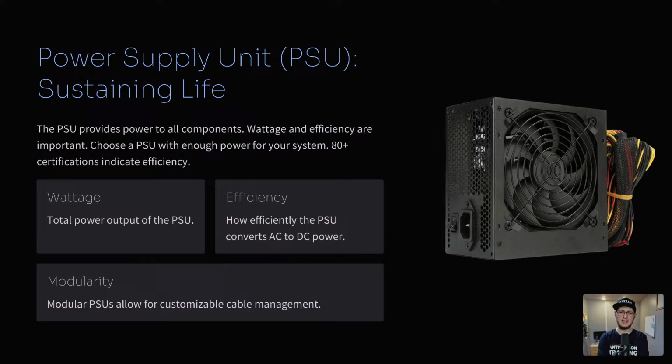And so you could find power supplies in like 200 watts, 250, 400, 500, and then higher end builds are going to be running 1,000 watts, 1,200 watts, 1,500 watts, and so forth. I feel for a pretty decent setup, you're probably going to be in that 600 to 800 watt range for a mid-tier setup. However, again, results are going to vary, which is why checking the compatibility and using one of those tools, or asking the community itself for some assistance, is worthwhile if you're not too familiar with it.